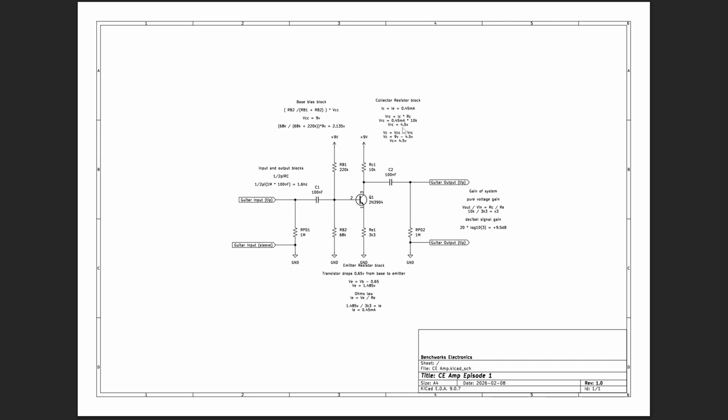Right? Which kind of makes sense, because if we want this to have symmetric positive up to 9 and symmetric negative down to 0, to have our sine wave not squared off or distorted at all, then we want this point here to be plus 4.5, so that then we can go down negative 4.5 to 0 and up plus 4.5 to 9.